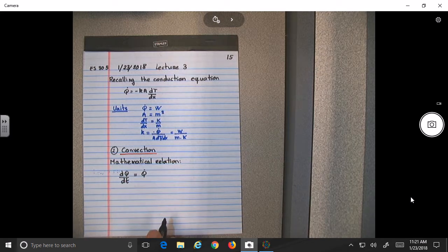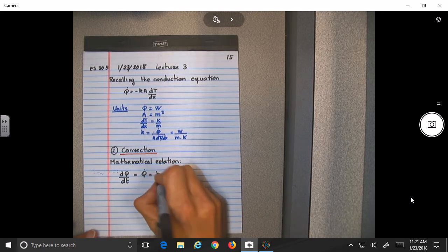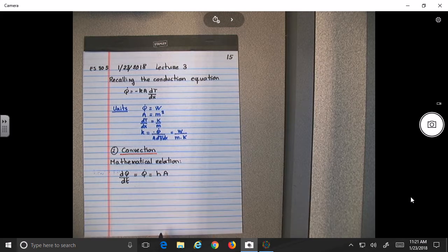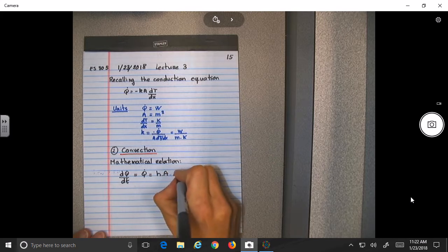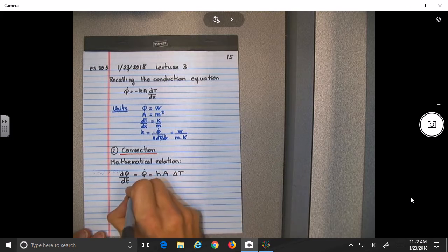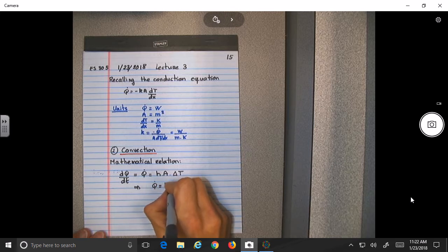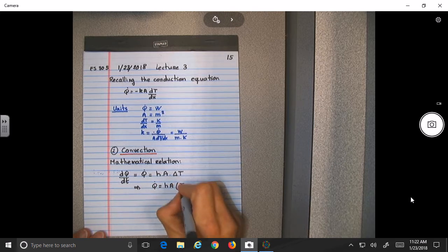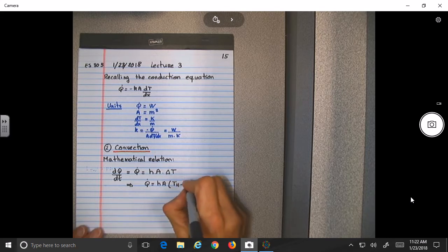So basically, it's the speed at which the heat transfer is going to go through a wall or through a medium, is H times A, and generally you write over here delta T, or we can just write HA. So what is the direction generally of the heat? It's going from hot to cold, no? So it would be that direction here.